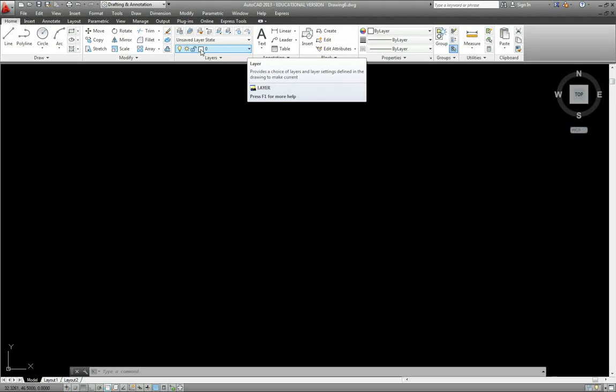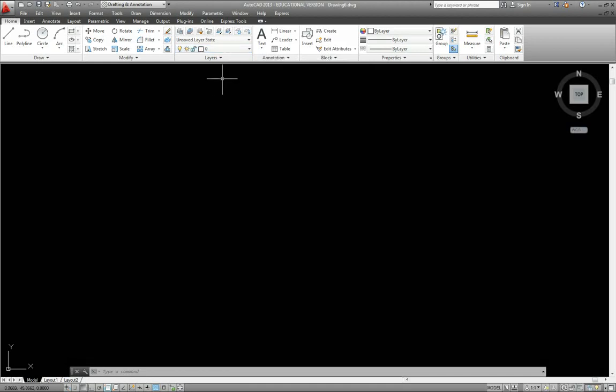If you're using the technical drawing text by Giesecke, the 14th edition, we are going to create a visible line layer. Visible lines are used to draw the outside edges of objects. If you turn to page 29, it's on the top of the page there. You'll see the visible lines are drawn thick with an approximate width of 0.6 millimeters. What we're going to do is create a new layer with those settings.